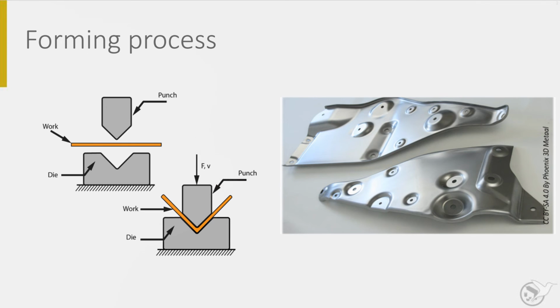For cars this is common, since the production numbers are huge, in the order of millions. For aerospace we should look for more universal processes, where processes and dies can be used for more different product shapes. Typical processes here are rubber forming and press brake bending. Sheet forming processes also encounter spring back. This is due to the elastic deformation of the metal sheet.